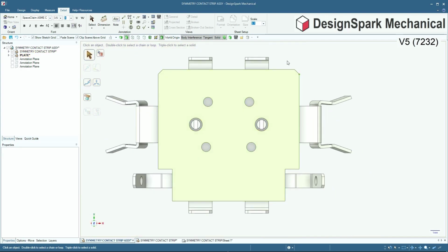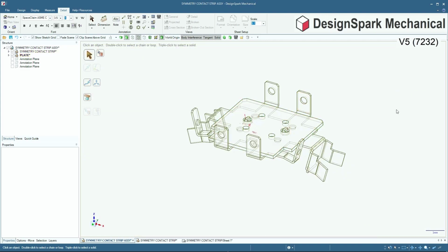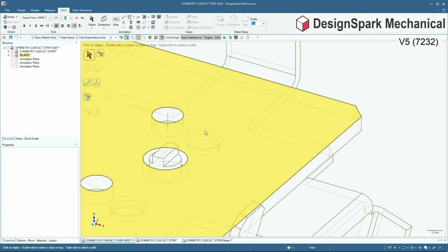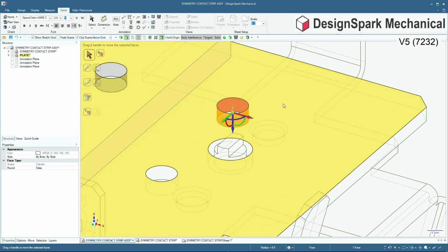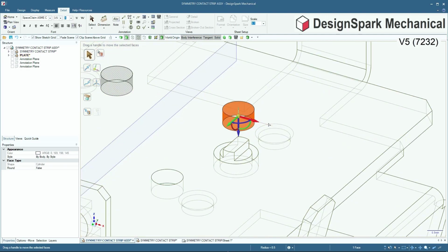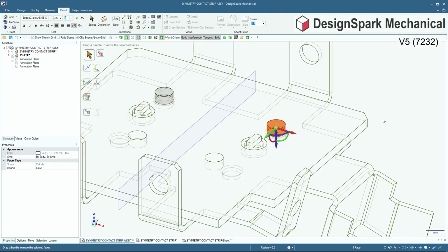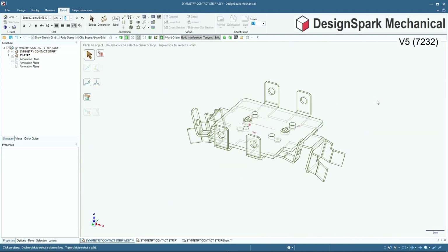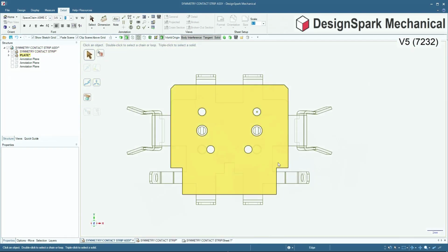Although a solid shaded view is highly visual for shape appreciation, it can also easily obscure misaligning holes. So let's go back to this view and let's now move these holes to line up with there. See what happens. So let's select one. Okay, I've only got one here. So again, let's go up to and move the cursor over the target object. Press Control and rotate the middle mouse wheel, and you can see it drives through, and that's fine. So if I now select that, that's jumped to it, and that's jumped to it. So let's go back to our previous top view, and as you can see, everything now lines up.